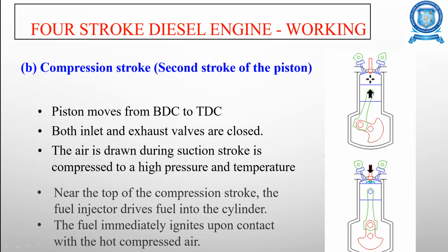And the second stroke is the compression stroke. Here you can see the piston moves from bottom dead center towards the top dead center. Both the inlet and the exhaust valves are closed. The air which was drawn during the suction stroke is compressed as the piston moves towards the top dead center, and the pressure and the temperature of the air is increased.